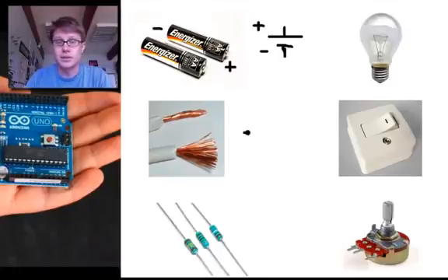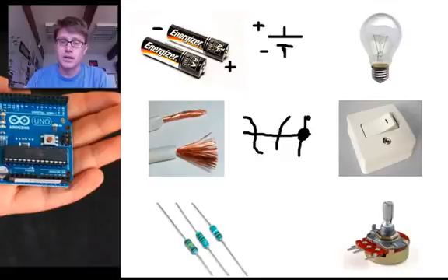Well, a wire is really simple. A wire is simply going to be a line in a circuit. Let me try to make it a little straighter than that. Sometimes lines will pass each other, and so we want to make sure we understand if those wires are connected or not. And so we usually put a dot here that represents that those two wires are connected. So this right here would be two wires connected, so electricity could flow through it. But if you just have wires crossing each other inadvertently, we don't usually draw that dot to connect them.